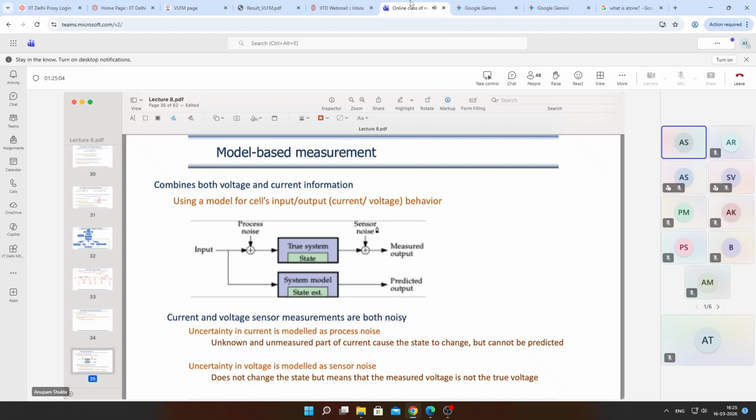Because there is going to be sensor noise. When voltage measurements are done, no sensor will measure accurately. So the measured value is actually the true voltage plus whatever bias or noise the sensor has. Therefore I do not expect my calculated value to be equal to the measured value, but I want it to be as close to it as these noises would allow.